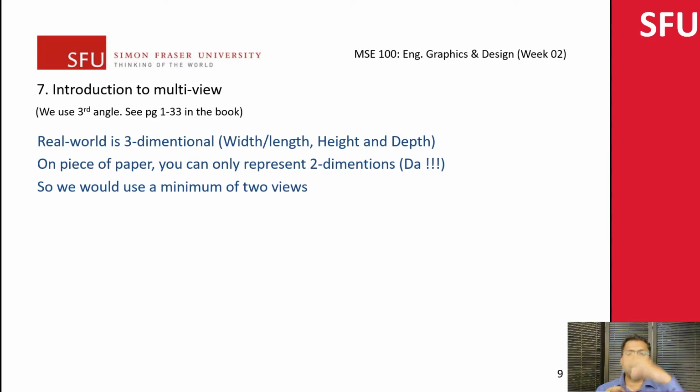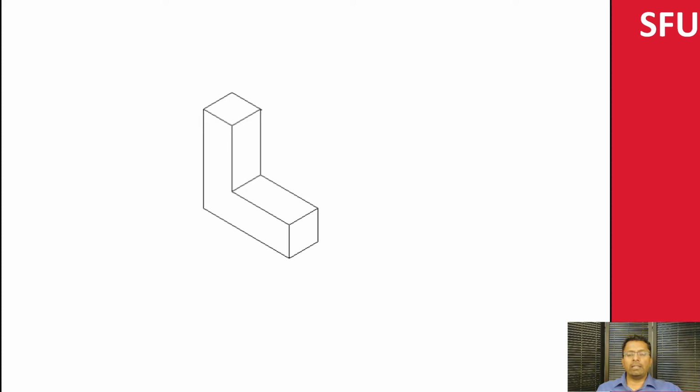So instead of randomly throwing the views, we have a visualization of how the views are set up, and that is given at the bottom of the sheet, but we'll nonetheless go over and see what is happening here. If I take the 3D object, this is again the L-shaped object, I'm looking at the object as such, and I'm essentially constructing a box like this for the object.